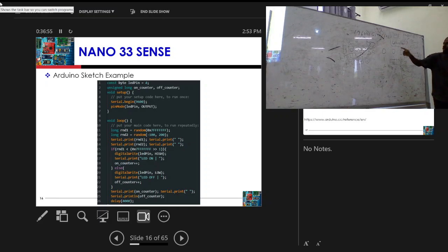Now, if I'm supposed to do the same thing with a divisor, you have to go through an algorithm, right? You guys know that. You have to go through an entire algorithm before it gives you the output. But with this one, you are just shifting and it gives you an output. So anytime you're dividing a number by 2, and that number can be 2 to the power of something, just shift.